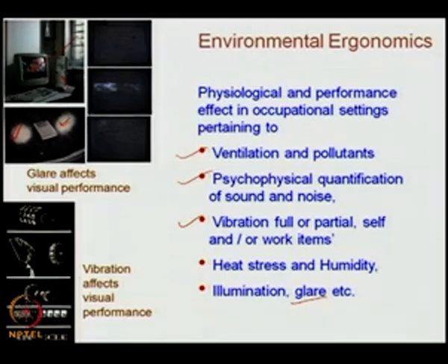Now, the surface and the lighting source have a direct relationship. In this case, with a specific light source and an angled surface, when the angle between the person's eye and the surface matches, it gives the maximum glare. So, either modify the angle of the source of illumination, or change the reflecting surface accordingly, and our glare effect can be reduced.